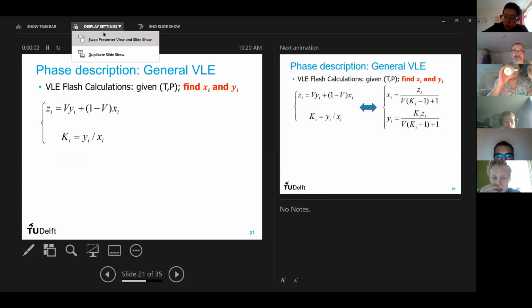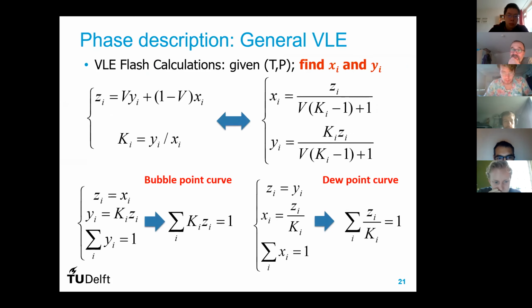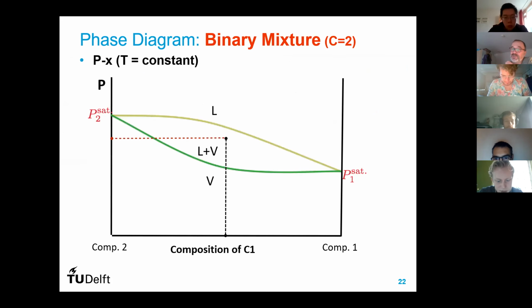Okay, so let's continue then with the rest. That was bubble point and dew point calculation. But now imagine that at this composition and this pressure, you estimate bubble and dew point, and it says you are in the two phase. So now you need to compute flash. You need to understand how this composition will split into the liquid and vapor.